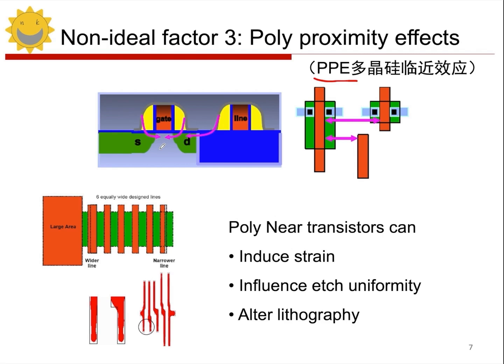During the etching process, there is an issue with etching speed, right? What affects the etching speed? It is actually influenced by the density of the polysilicon. For example, take a look at this diagram. We can see that we have drawn 6 gates. Let's assume these 6 gates represent our 6 fingers. We are making this transistor with 6 fingers, right? Originally, when we designed it, all 6 fingers were identical. When we laid out the design, these 6 polysilicon areas were also exactly the same, right?